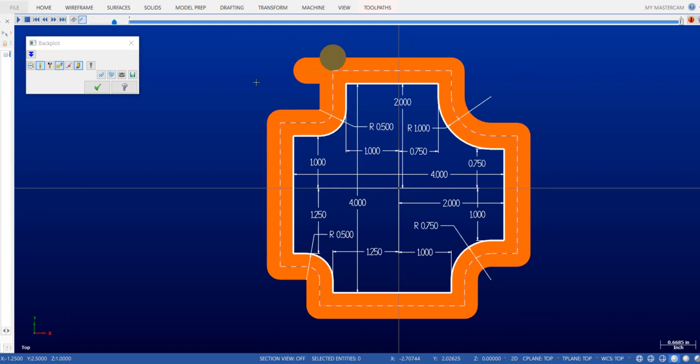Alright, so let me show you what the toolpath is going to look like. It is only going to affect the finish pass, where we're going to have to add this extra move, and then I'll show you what code to add on that line to actually activate the cutter compensation so that we can make minor offsets to change the dimensions of our part.